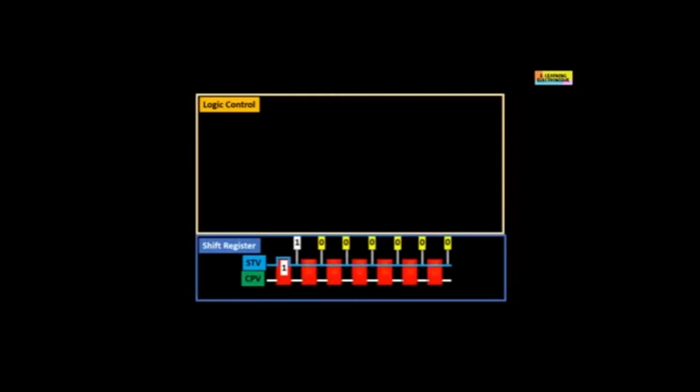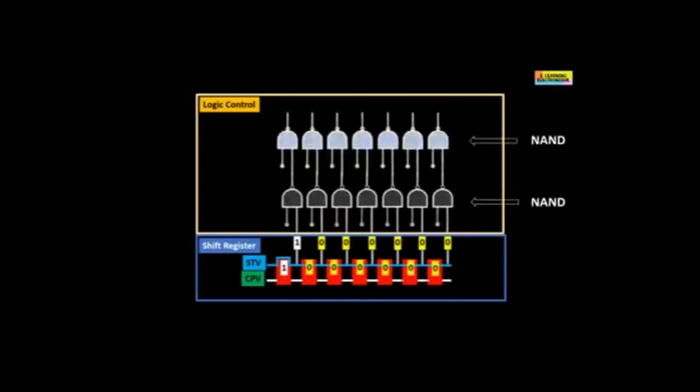The logic circuit of the gate driver is made as follows. According to the number of shift registers, as many NAND logic gates are placed in series. There are two successive layers of interconnected NAND gates. The first series of NAND gates is under the control of the OE digital signal, whose role will be seen later in this video. In front of the output of the OE signal is placed another logic gate NOT, which will invert the signal. On the second line, all the NAND gates are under the direct control of a digital signal called XAO, the meaning of which will also be explained later on.